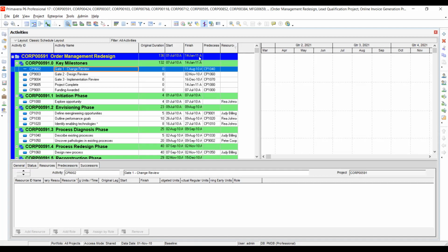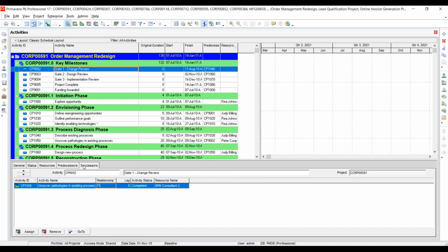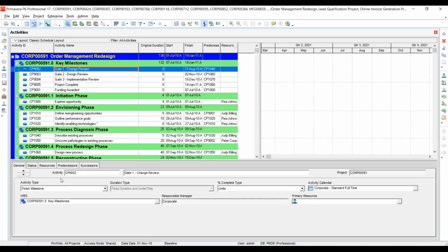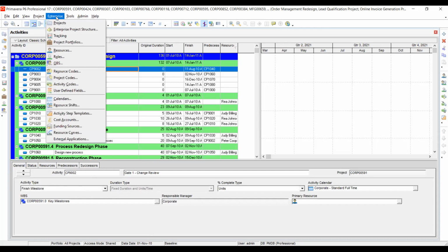So any questions about that? Nothing, I think it's fine. Only maybe predecessors, successors, the leads and lags. I think we'll do them when we reach there, we'll revise them. But generally, start on EPS, create OBS, create the project again, go to work breakdown structure, create activities. I think I'm good.